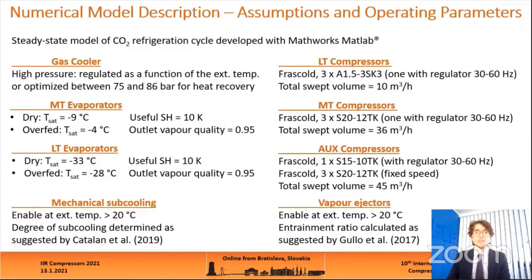A steady-state model has been developed in MATLAB, and some results obtained from the monitoring of the system have been used as boundary conditions. The number and type of compressors are the same as the monitored system. One compressor of each group is equipped with an external inverter with frequencies between 30 and 60 Hz. With the overfed evaporators, the evaporating temperatures are increased by 5 Kelvin compared to dry expansion evaporators, and a vapor quality at the outlet equal to